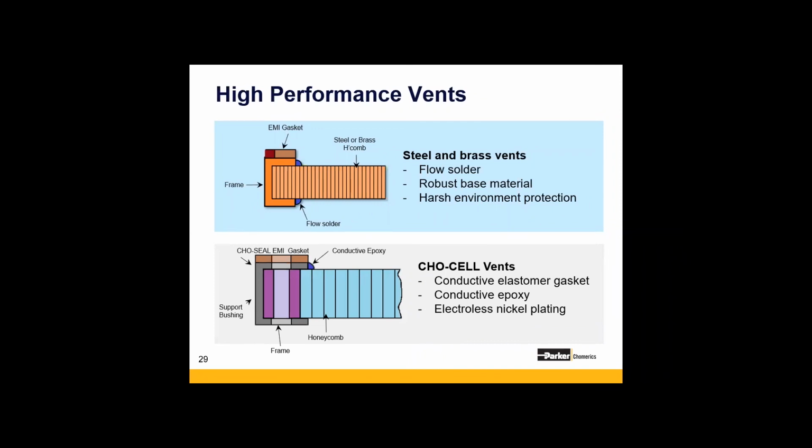But also a really important feature is the benefit of maximum H-field shielding effectiveness. It can be very difficult to shield and absorb at very low frequencies with traditional EMI shielding materials. So steel is a very good candidate when I call the H word, H-field shielding is needed. So something to know.